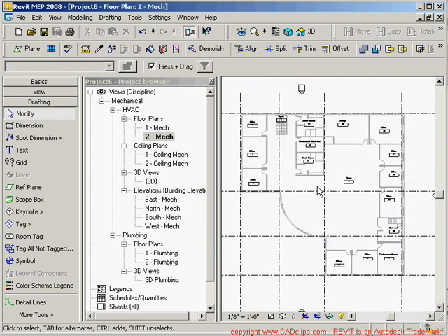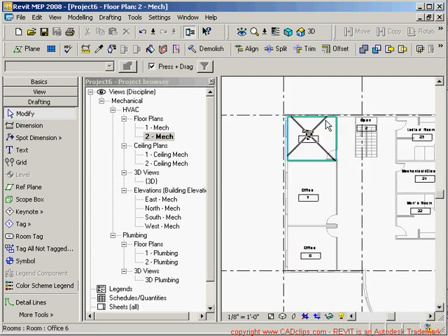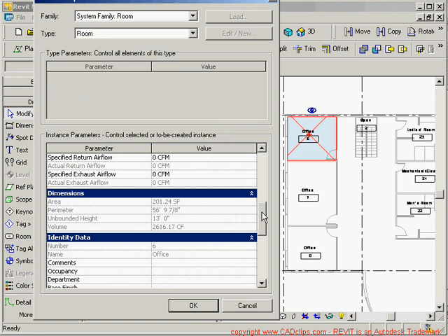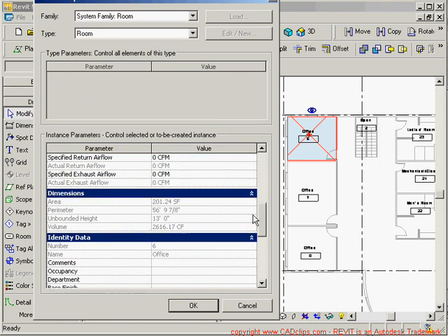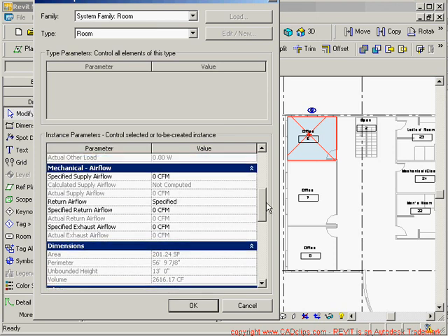And now let's look at the properties of a room. So if we hover over a room, the way to pick it is you hover and you'll see that X. You click on it, and then we go to this properties button, which we use, element properties, constantly throughout using Revit. And we click on here, we have all these great properties of the room. And this is where all the fun begins, because we can go in here and we can see that the volume of the room is a certain amount of cubic feet, and because we're using imperial units, the area, the perimeter, bounding height, and we can talk more extensively about the bounding heights and what is room bounding and what is not.